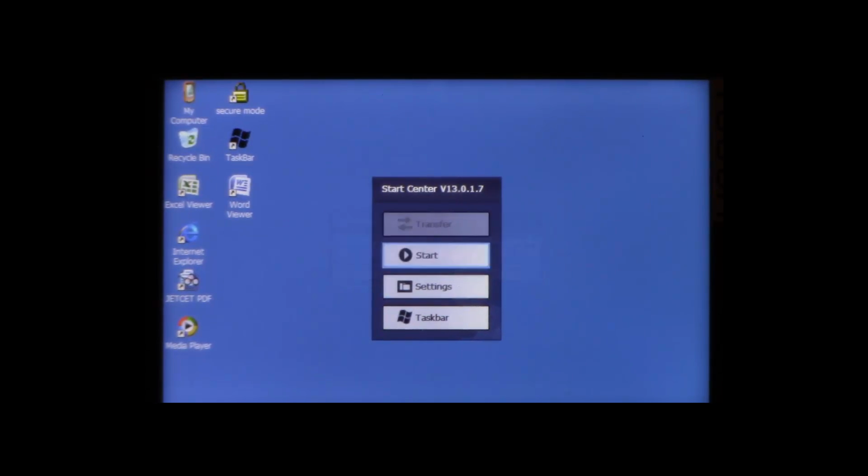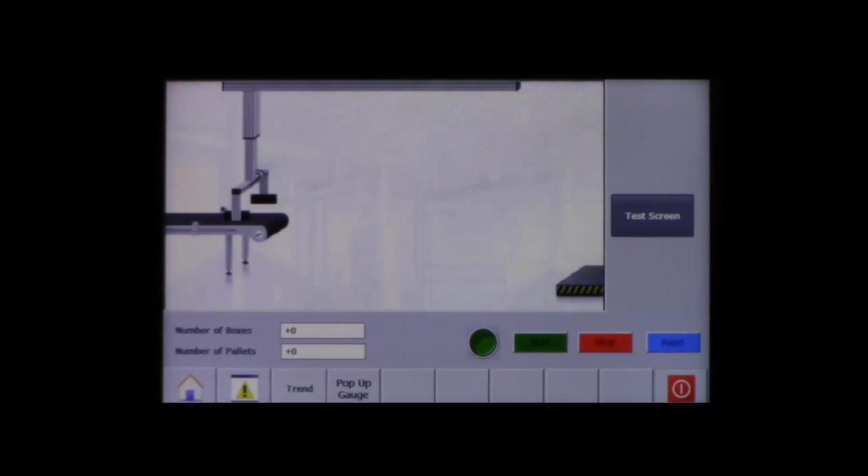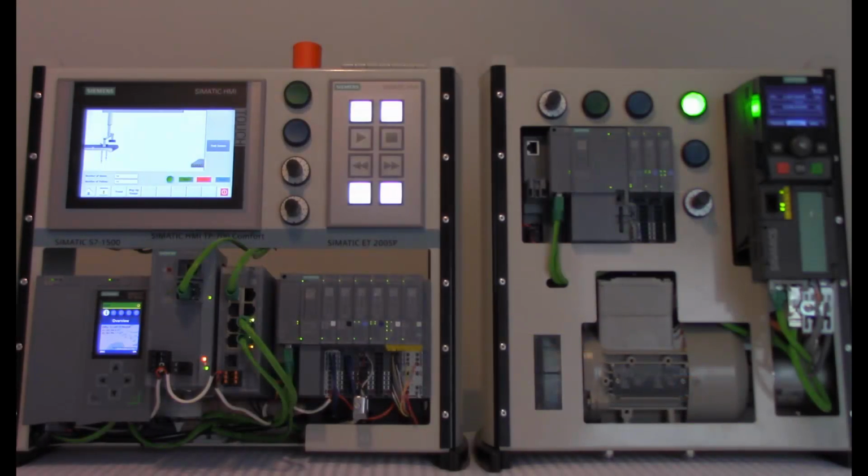When the process completes, you will now have a full and complete backup of that HMI device, including the licenses. So long as a Simatic HMI memory card remains inserted into the system slot, it will continuously back up the HMI device, which will give you complete protection in case the device gets damaged. And so now we know how to back up our PLCs and our HMIs. In the next video, I will show you how you can replace your devices and then use these SD cards to restore them back to working order.